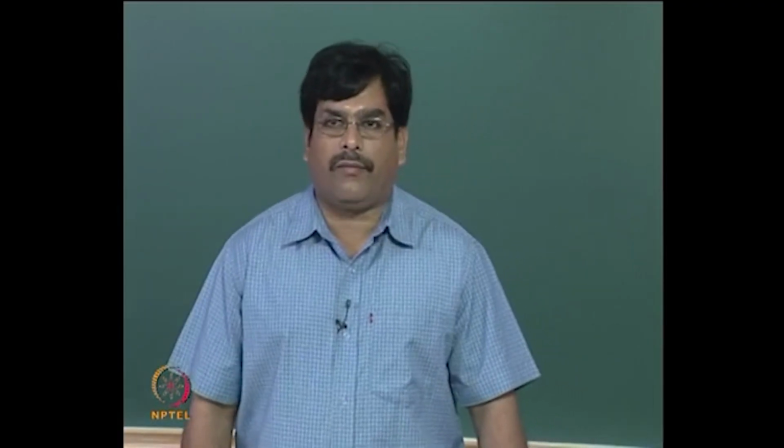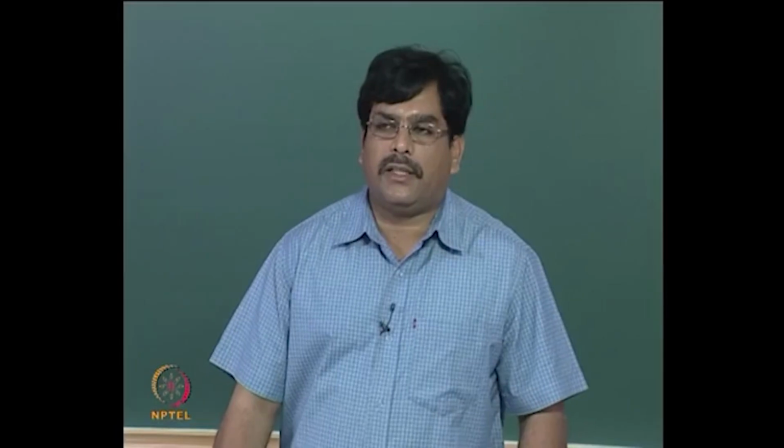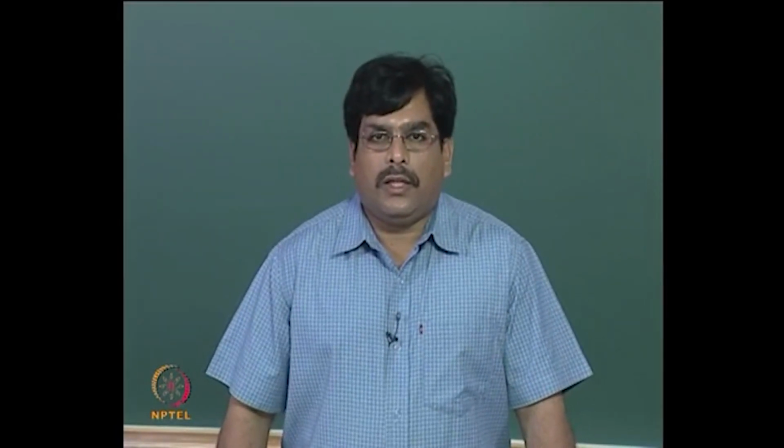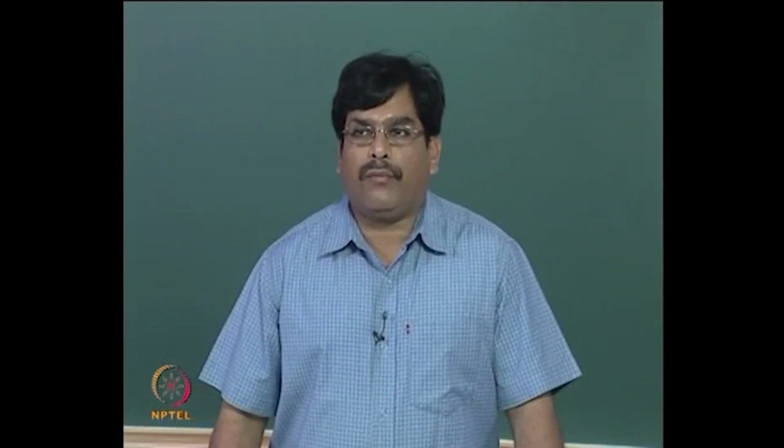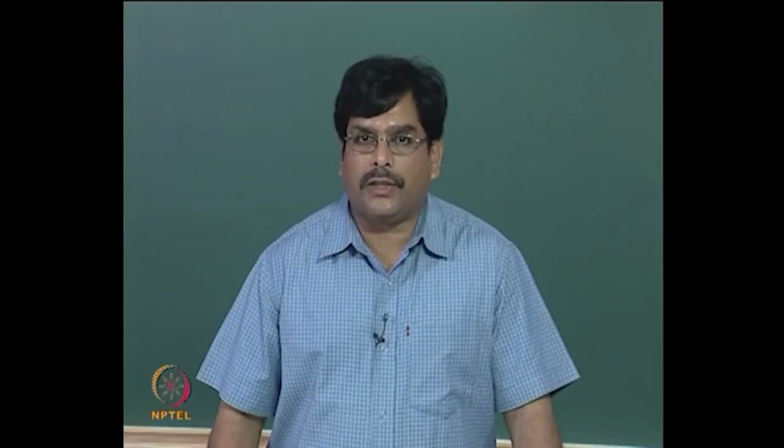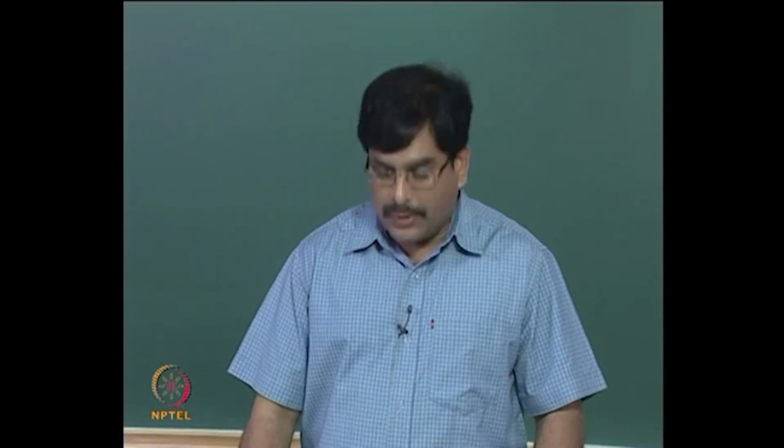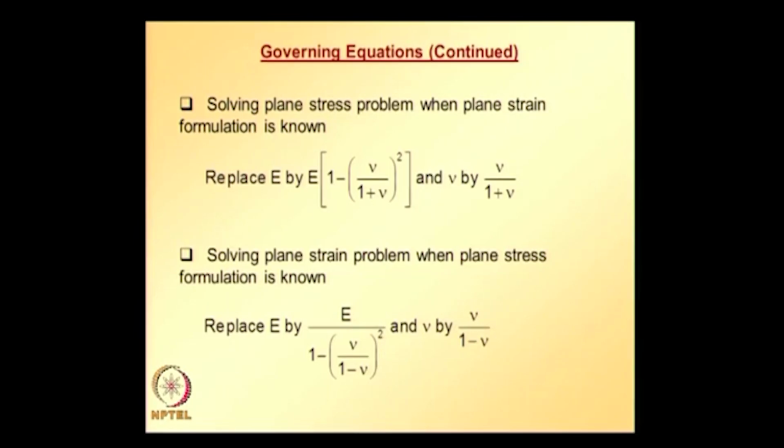other problems, first we need to come up with, if we are using variational formulation, an equivalent functional, or if we are using the Galerkin criteria, then we need to finally bring the governing differential equation and boundary conditions to such a form where we can substitute the approximation of the trial solution and the derivative of the trial solution.